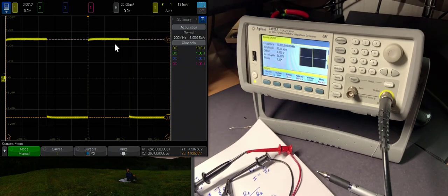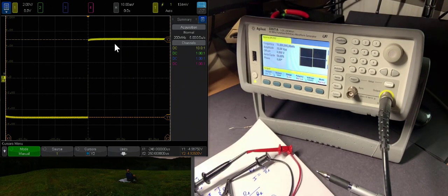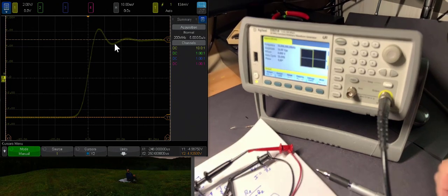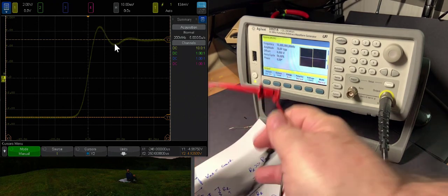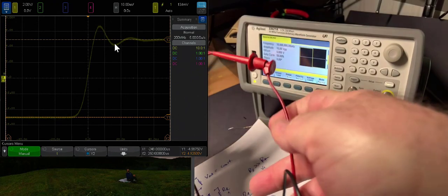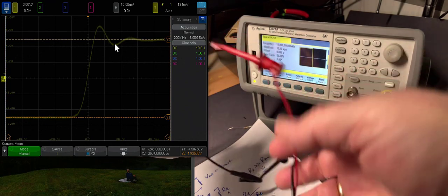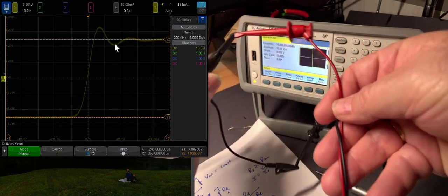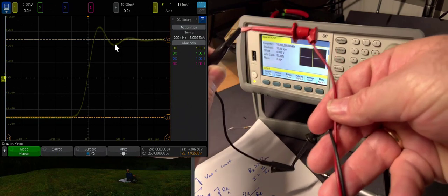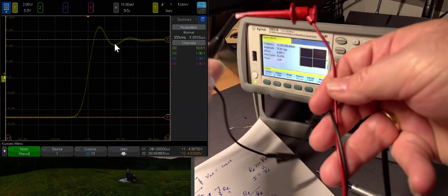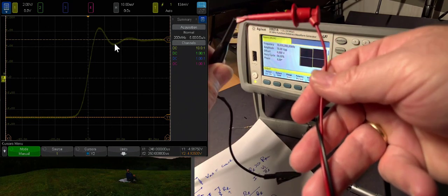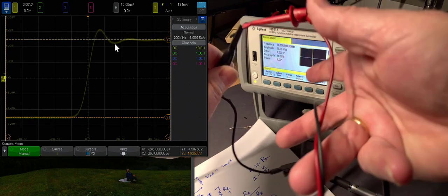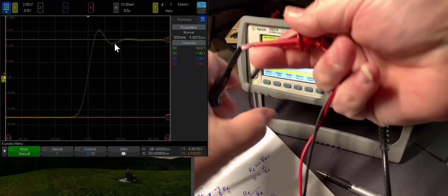If we zoom in on the rising edge, we'll notice another small anomaly. Let's zoom in and look. We have some ringing here. We didn't have that when we looked at the signal with the coax. And that's because we've got this whopping big loop over here, and that's distorting the signal. This is the first example we've seen where the electrical properties of the interconnect affect the signal. This interconnect, for this rise time, roughly the 8-9 nanosecond rise time, is not transparent at this rise time. And you can see that by changing that loop, by adjusting it.